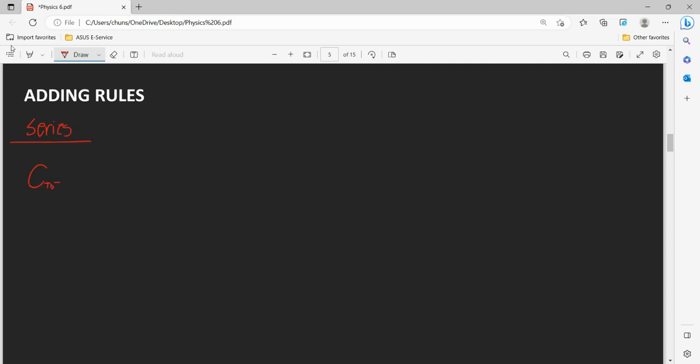So our total capacitance is equal to the sum of all of our 1 over capacitance, to the negative 1. Now, if we are in parallel, we are going to be adding just as is. So it's just the sum of each individual capacitance value.